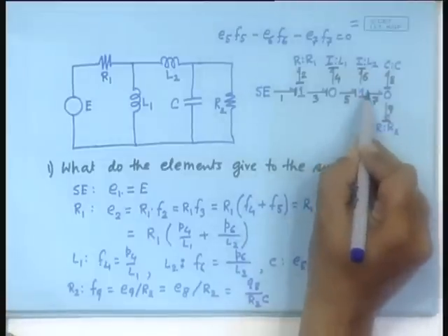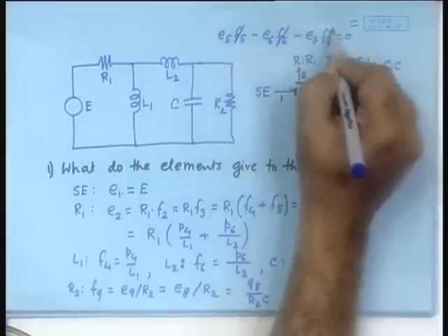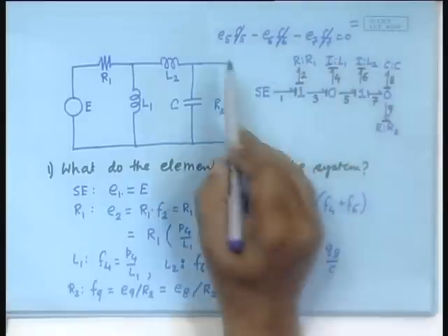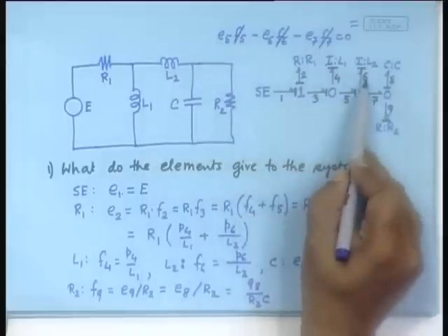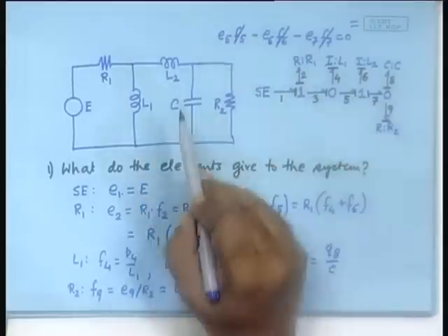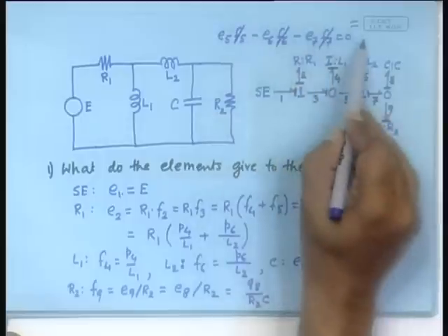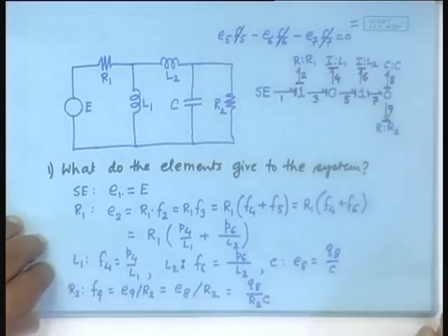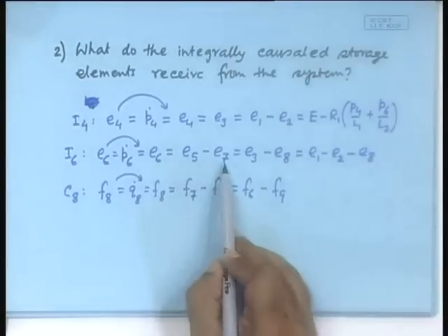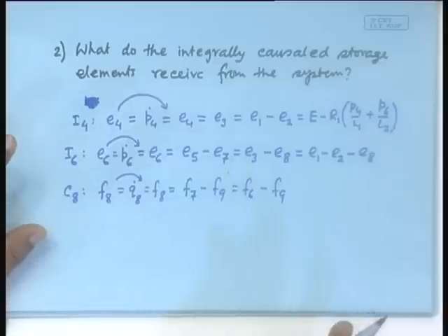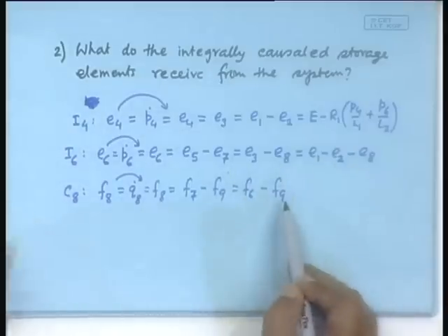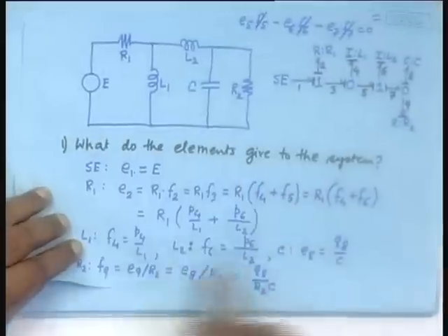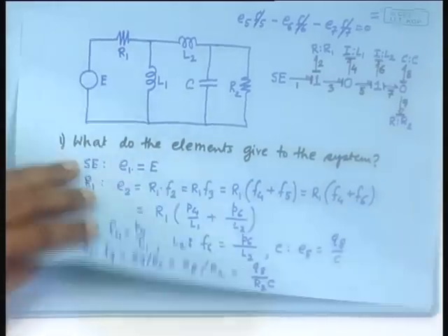Now, it is a 1 junction, which means the flow equalizing junction, which means the flows are all equal, they cancel off, which means we were interested in E6. So, E6 goes this side, which is E5 minus E7, is that right? Okay. So, E5 minus E7 was correct. Fine. Have you understood the procedure? Then all these are known from this, so you just substitute, you get the equations.